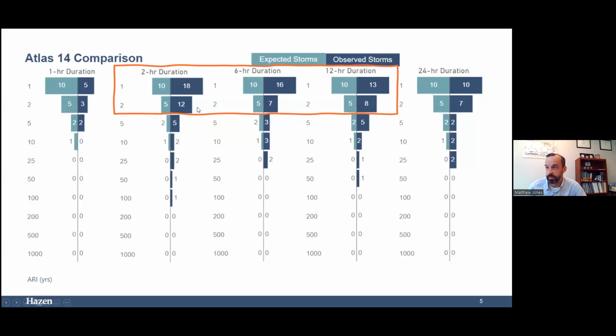One, we saw some relatively short duration, pretty large events, up to 100-year. Generally, we don't reasonably expect our green infrastructure and bioretention to be doing much for that type of event. But it's also notable, and highlighted in the box here, that some of the greatest departures from those Atlas 14 averages are in the more frequent and also shorter events.